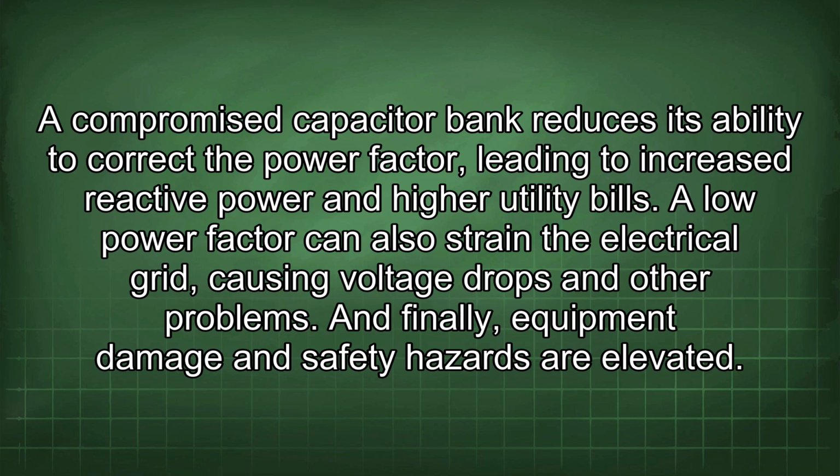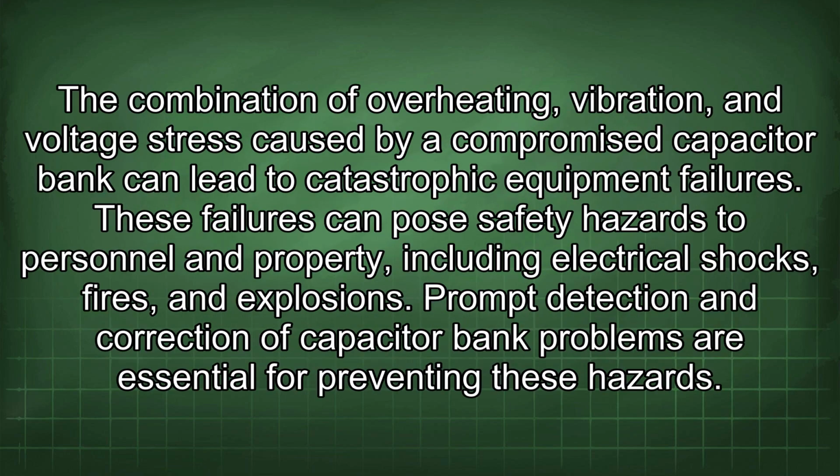And finally, equipment damage and safety hazards are elevated. The combination of overheating, vibration, and voltage stress caused by a compromised capacitor bank can lead to catastrophic equipment failures. These failures can pose safety hazards to personnel and property, including electrical shocks, fires, and explosions. Prompt detection and correction of capacitor bank problems are essential for preventing these hazards.